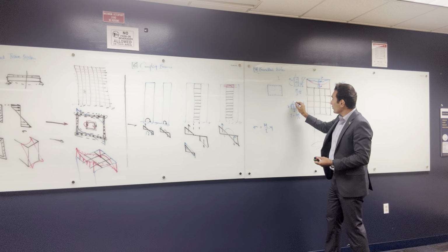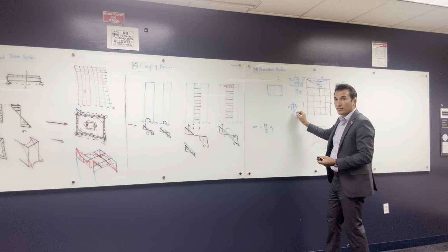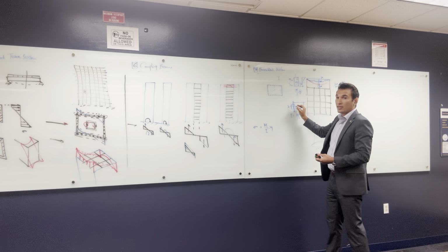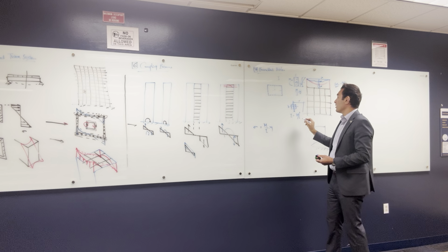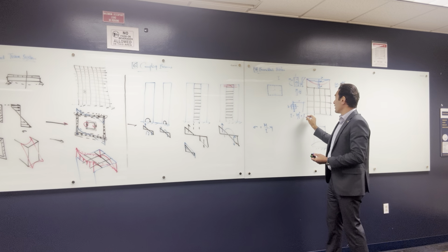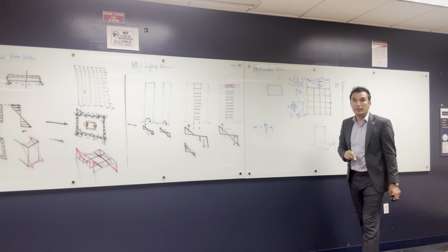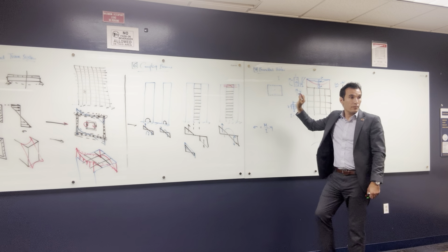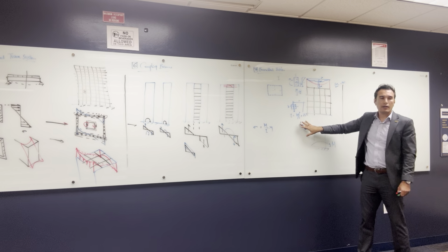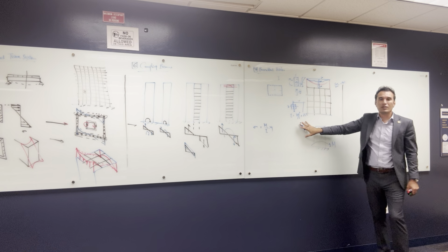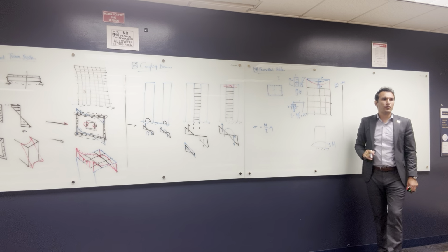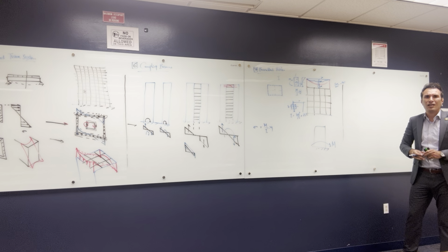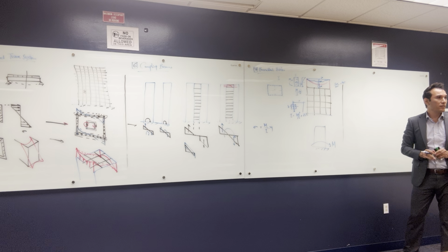So you find the moment of inertia about this axis and then multiply the area of this cross section by this distance squared. This is r. So it's going to be plus the area multiplied by r squared, right? I'm just trying to remember. I don't have the inertia formula here, but if you search it online, you will find it anyway. This is in many materials. You studied it in dynamics and in mechanics of materials.